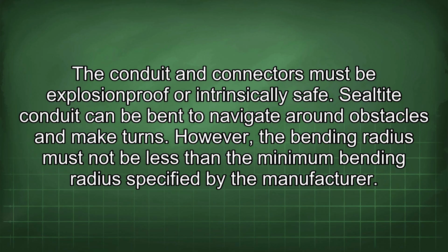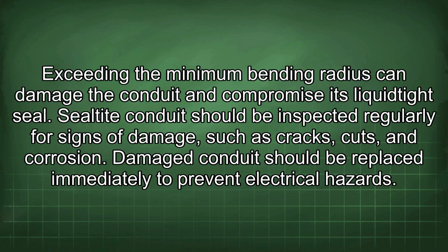Sealtite conduit can be bent to navigate around obstacles and make turns. However, the bending radius must not be less than the minimum bending radius specified by the manufacturer. Exceeding the minimum bending radius can damage the conduit and compromise its liquid-tight seal.